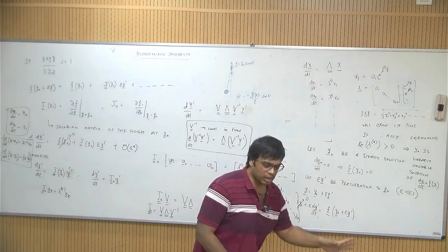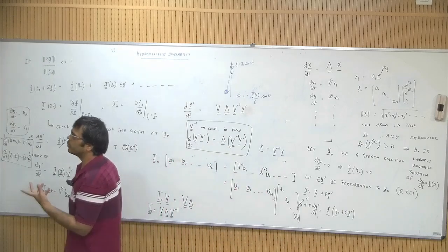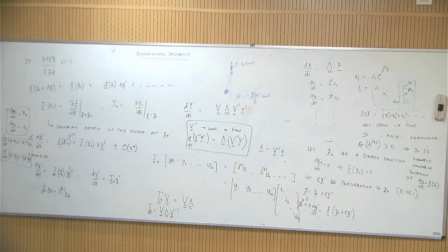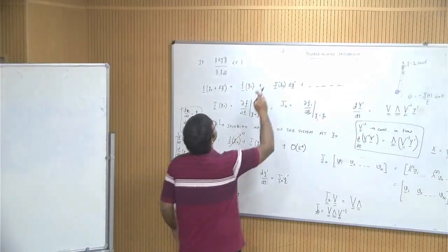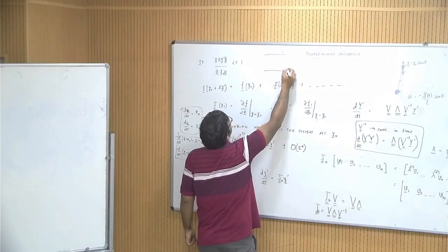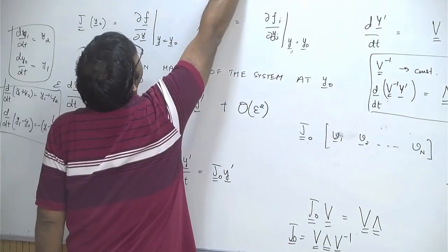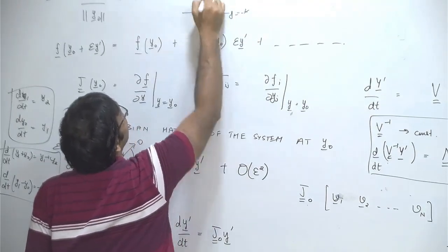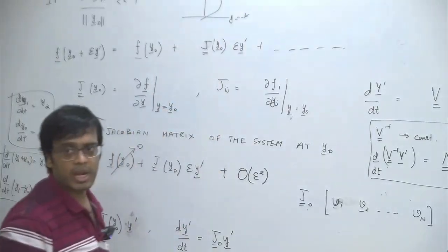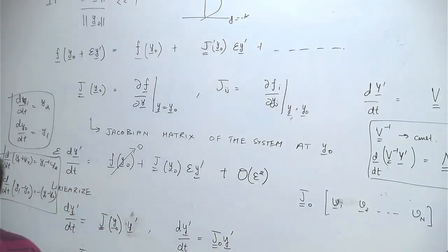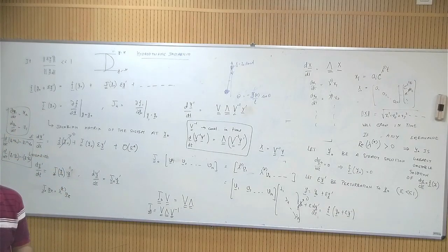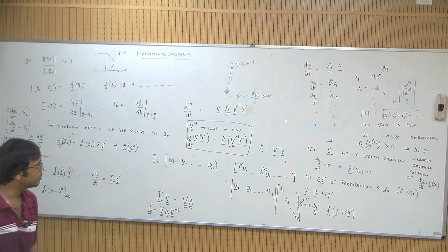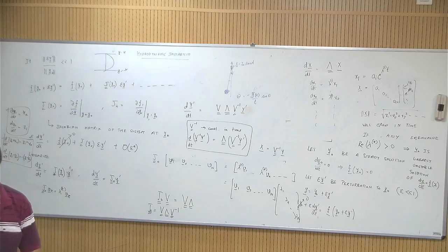Now, how is all of this connected to fluid dynamics? As we will see that in some cases the laminar flow solutions that we have found, even the simplest laminar flow solution, which is, let us say, your flow in a channel. Okay, if you have, let's say, this is y equals h, you have y equals minus h, then you know that this profile is parabolic in nature. Even in the simplest of these kind of examples, if you consider some form of perturbations, they will be unstable.